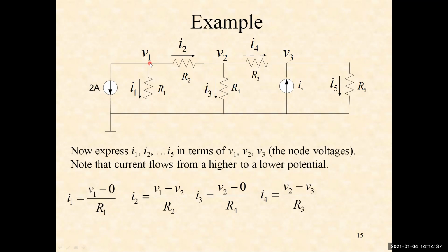So by using nodal analysis, we are finding the node voltages based on the concept of Kirchhoff current law. Understood? Nodal analysis is related to Kirchhoff current law. Mesh analysis is related to Kirchhoff voltage law. Mesh or loop, that is related to the KVL. But nodal analysis, Kirchhoff current law. By using KCL equations, we have to find the node voltages. So we will get equations in the form of voltages.